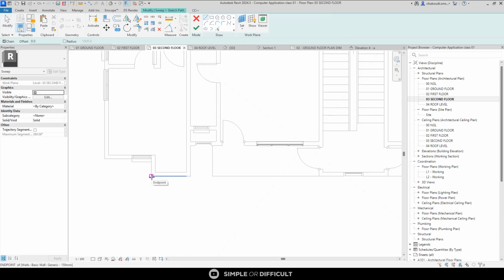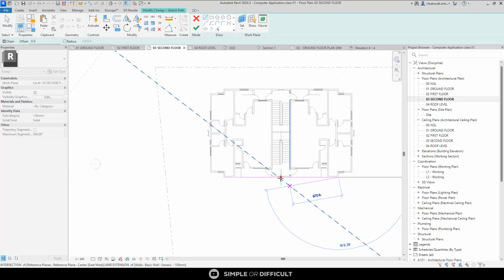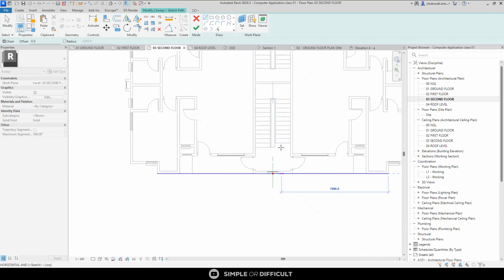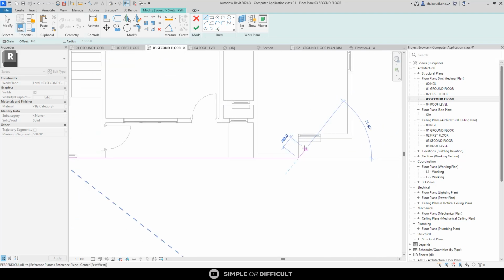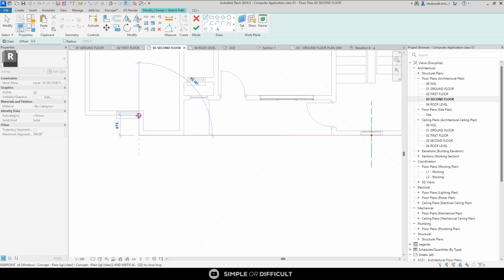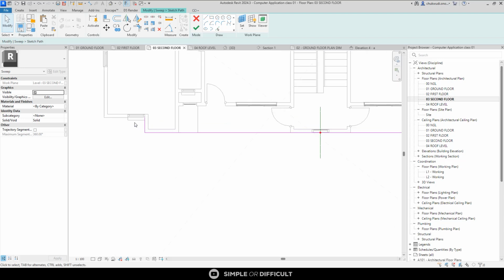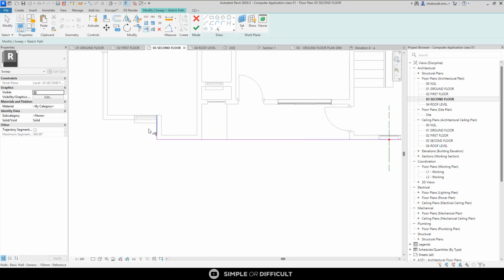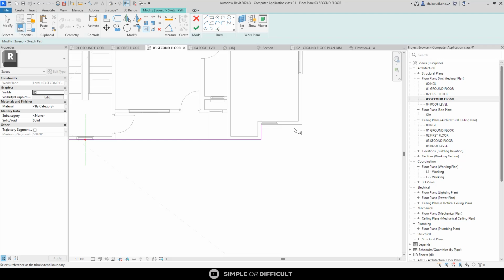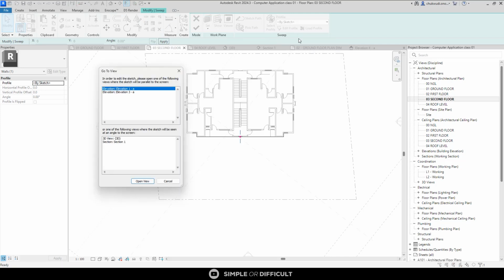I want to be able to model this thing on this other side. So that means I'll be on this elevation when I'm modeling it. This is the plane where I'm going to model it. Right. So I'm going to end it here, so when I do my sweep, it sweeps the profile I'm going to model around this path. Okay. So yeah. So I will say, okay, I'm done with creating the path. Let me now create the profile.